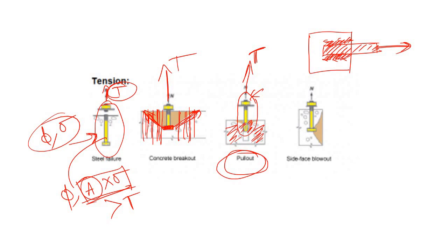So just to resist this pull out, you have to ensure that there is sufficient embedded length of the anchor bolt. If the embedded length is very less, in that case your anchorage may fail under pull out action. But if you have sufficient length as well as end anchorage in terms of some washer or bolt, then this tensile force cannot pull out this anchor. Okay, so that's it.